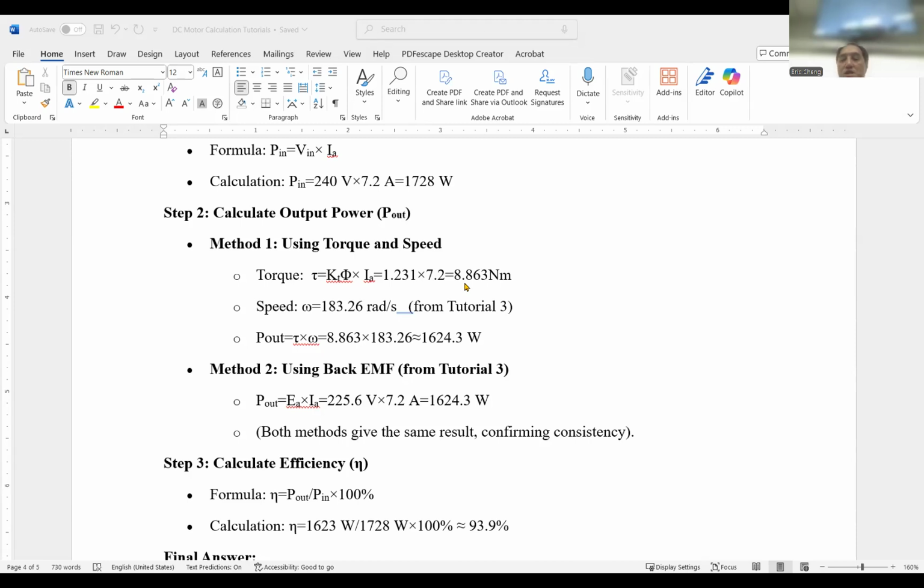So the initial braking torque. You see now the current is not going inside the back EMF, but going outside the back EMF. So that's why in operation we consider it as negative. Positive means going inside the motor back EMF. Negative means going out. So the torque here will be, you see the torque constant is unchanged even though we are changing from a different mode of operation. Torque constant looks more like a physical parameter inside the motor. So this is multiplied by the braking current, which will be this one.